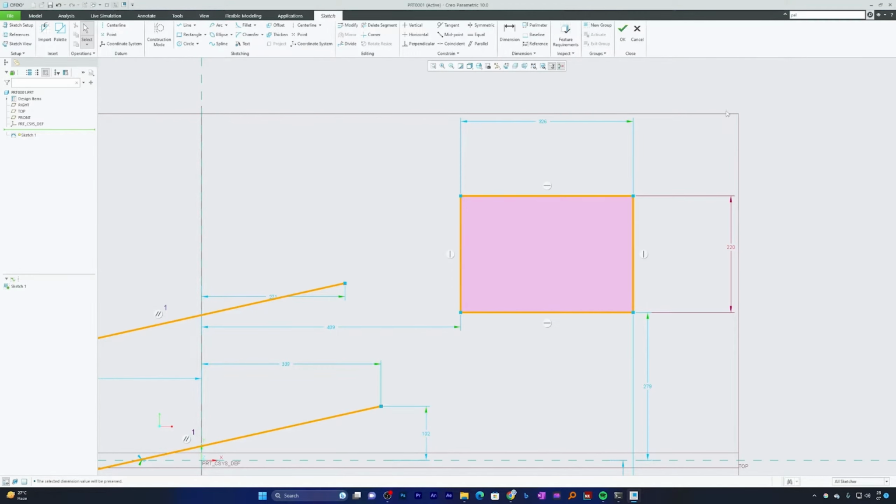There is also a setting in PTC Creo Parametric which will turn on locking by default as soon as you change the value. For example, as of now, if I change this value, it will turn royal blue from sky blue, which again shows that this is a modified dimension and has now been converted to strong, but it is still not locked.